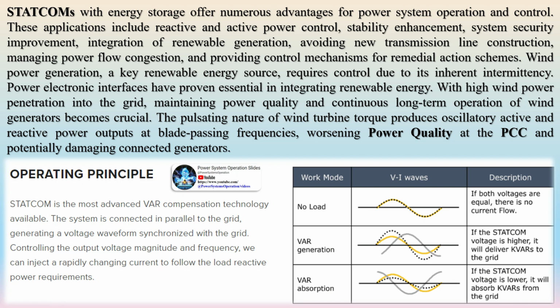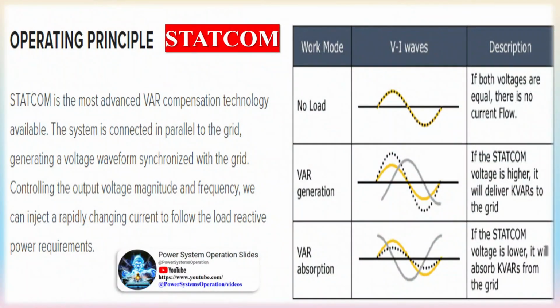When distributed generation DG power exceeds the maximum that can be injected into the power system, the battery absorbs the surplus. Conversely, if power consumption is high, the battery supplies the necessary power. If the battery is fully charged, a dump load can absorb the excess power, while excessive consumption can only be managed by limiting power. STATCOMs with storage also provide low-voltage ride-through capability and reactive power compensation.